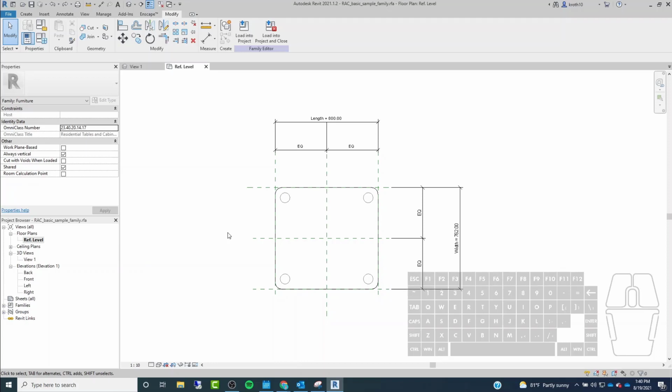And then maybe we have a slightly altered version that has slightly different dimensions that we can use as a coffee table, and then maybe a third one that we can use as a dining room table. If we don't want to go out and find those actual different families, we just want to get a quick concept out and we just want a space plan, we can just use one family, and we can create a bunch of different versions of that family and toggle through them and then put them wherever we want in the space to get an idea.